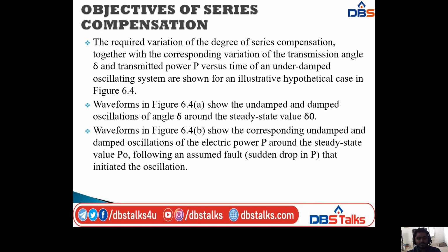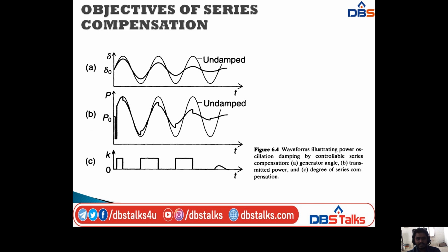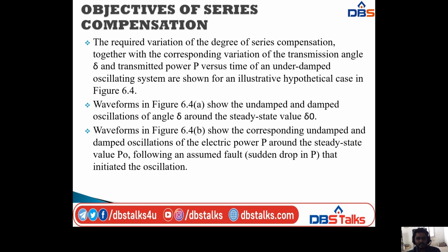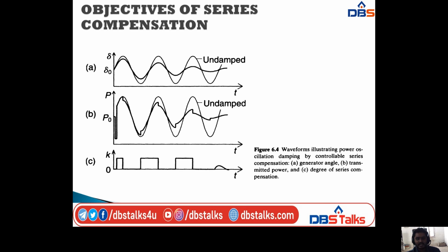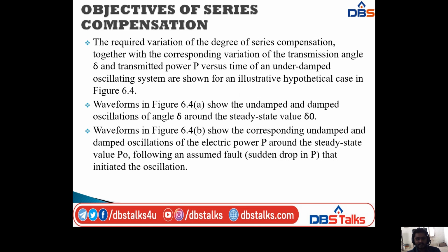The waveforms in figure 6.48 show the undamped and damped oscillations of angle delta around the steady state value delta naught. So this is the first diagram, and it is an undamped system. It consists of the waveforms with an undamped and damped oscillation of angle delta at steady state value delta naught.